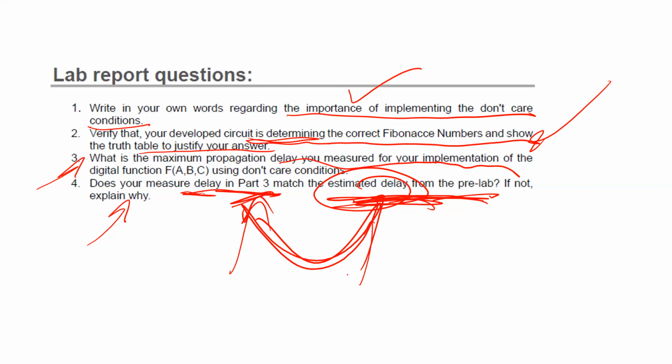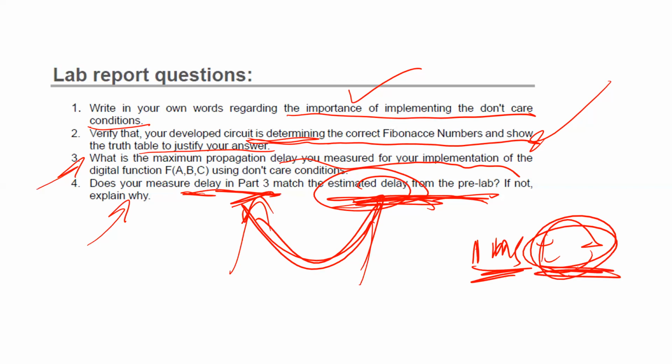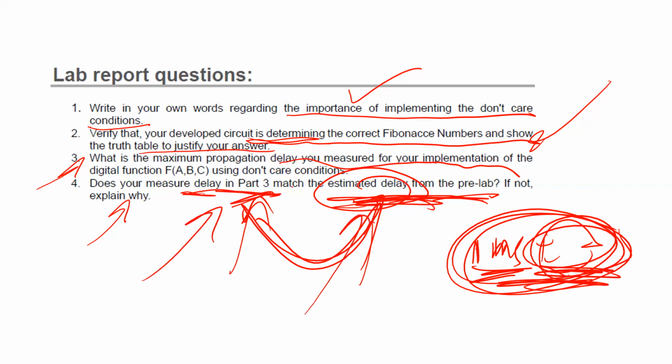That's why there may be some variation. So if the data sheet tells you 1 nanosecond plus or minus something, that is because it's impossible to create something exact for all chips. That's why there is already some margin of error. All of these reasons make the delays not identical, but they should be close enough. I think this lab should be easy, and good luck.